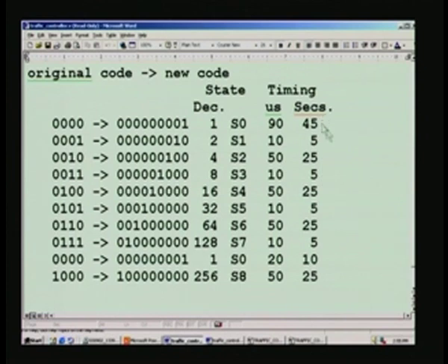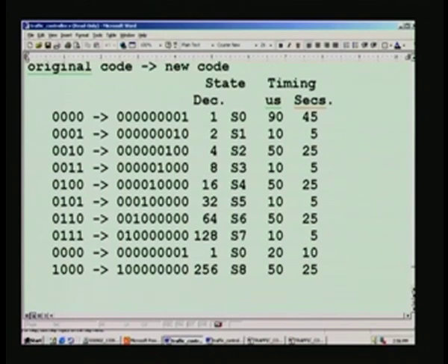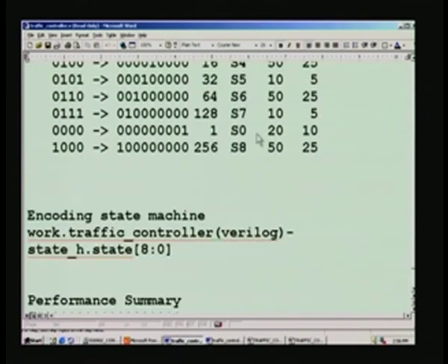I would recommend that you go through all these simulation signals after back annotation. All these results are once again after back annotation. Back annotation is what we get after gate delays are incorporated, after Xilinx place and route; you have to do back annotation and then simulate. That is the real picture, and otherwise you will be mistaken, thinking that it will give a high frequency of operation. That is not really correct unless you do the back annotation, as I have insisted all through.